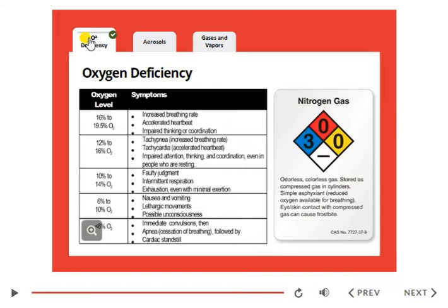Oxygen deficiency can occur when air is displaced by gases and vapors heavier than air, or when the oxygen is removed by an oxidizing process, such as aerobic action, combustion, or rusting. Without an adequate concentration of oxygen in the air, the worker is in an immediately dangerous to life and health atmosphere. Normal breathing air is 20.9% oxygen, and the Clean Harbors policy requires respiratory protection in atmospheres below 19.5% oxygen. Permit spaces such as boilers, vaults, and sewers are examples of possible oxygen-deficient work areas. Oxygen-deficient atmospheres may cause a person to feel lethargic and potentially lose consciousness.